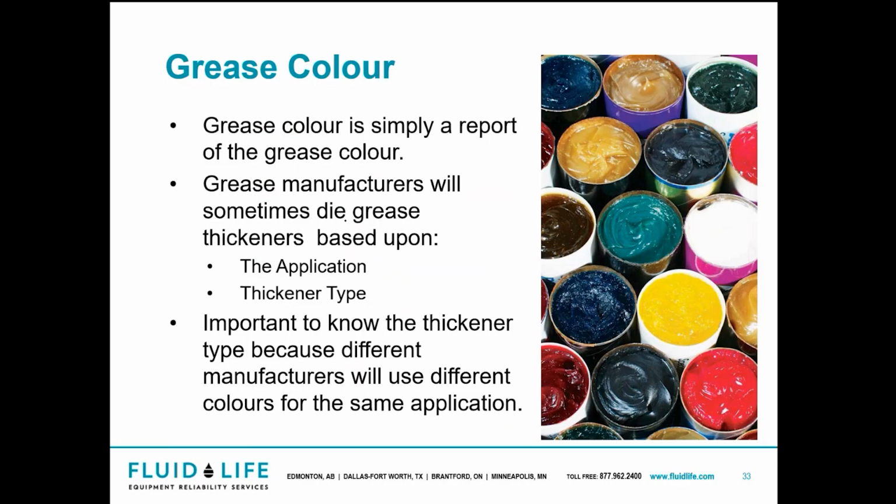Now, grease color is basically a symbol of the grease report. So you can see, like in my stock image here, grease manufacturers sometimes dye their grease, and it helps with identifying the application and the thickener type. You need to know your thickener because manufacturers may use the same colors for different applications. I've seen that run into problems where